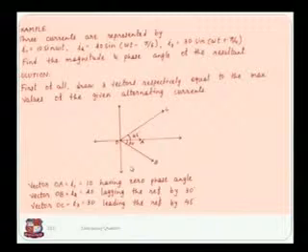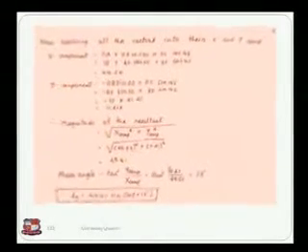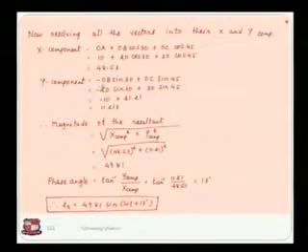So whenever you find the y component for OB, then you have to consider a negative sign over here. So here it is minus OB sin 30, because this is lagging current. If it is leading, then here it is positive. Because this is the lagging current, so here it is negative. So it is equal to minus OB sin 30 plus OC sin 45.